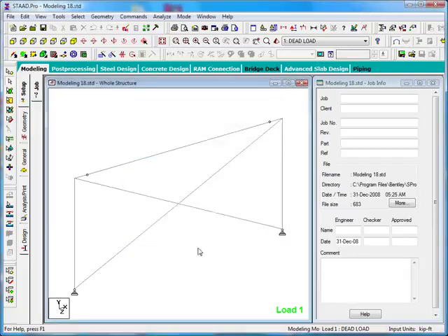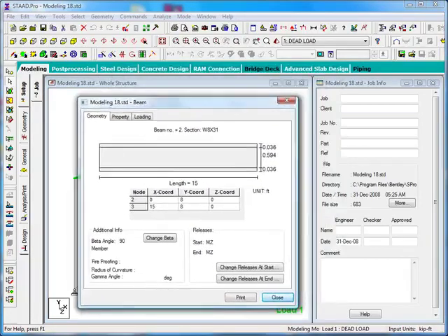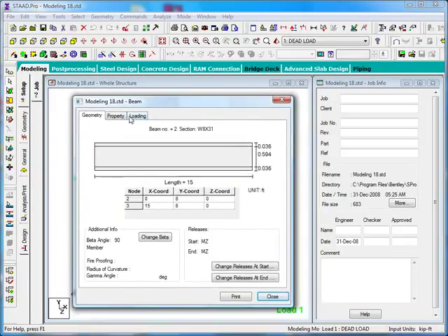I'm going to just close this dialog and go to the next thing that we have available to us for viewing structure geometry, and that's what we call the query function. What I'll do again is use the beams cursor, and I'm going to come up, and this time I'll double click on this horizontal member. When I do that, we get this query dialog box that opens up specific to this particular beam. It happens to be beam number 2, and it shows us information about the section, gives us some geometric information, gives us the end nodes and the coordinates of those nodes, and then more information that's available down here to describe this particular beam in the model.